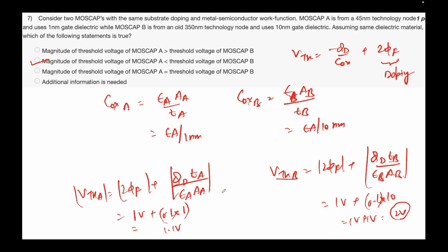Then I am applying a very small AC bias with voltage of magnitude Vs and frequency omega. There will be a change in charge denoted by this delta q. This delta q directly corresponds to the change in the AC voltage that is fluctuating. The DC will not change; DC is given by Vg. Vs is small, so compared to Vg, the change will be only minimal, which is denoted by these black squares.